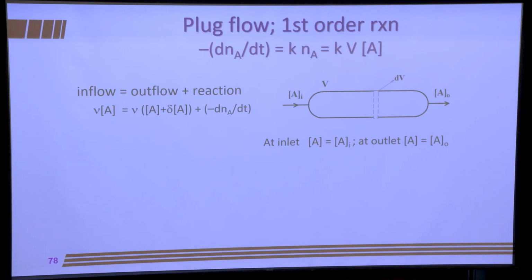And so we have the flow rate times the concentration of A is equal to the flow rate times the concentration of A plus whatever change there is in the concentration of A, which will be a negative value, okay? Plus the change in number of moles, this is the reaction. Okay, so we have inflow is equal to outflow plus reaction. Is that all right with everybody? Okay.